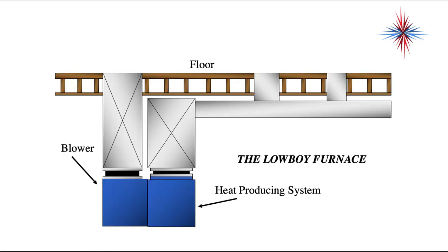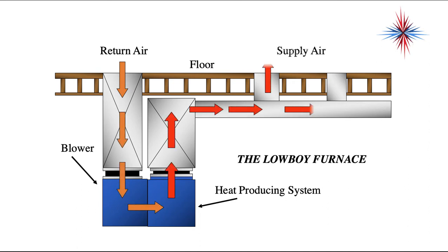By the lowboy, this is what we're talking about. The furnace is a really low one. You have the blower compartment mounted almost next to or behind the heat exchanger. And both the supply and the return ducts come in from the top. So we bring our return air in, we come through the furnace, we heat it up on the heat exchanger, and the supply air pushes out.